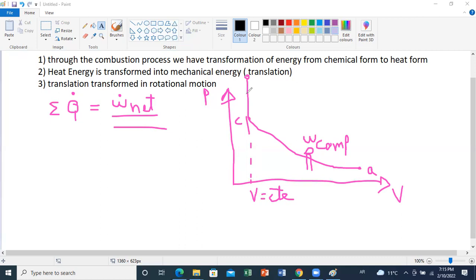Okay, if we think in a logical way, you have heat that will enter your system due to combustion. Now, to know why we don't have work, try to remember some formulas related to work. You remember for work, what was the formula for a certain process? It was P times delta V, because there's no change in volume, so it's zero, so work is zero. Very good.